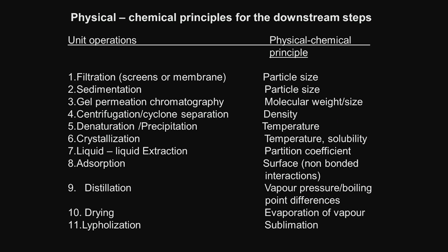For example, filtration, if you take, it works on particle size. So, larger particles are stopped on top of the separating filter cloth, smaller particles go through. Sedimentation again is based on particle size, larger particles settle down. Chromatography, for example, gel permeation chromatography works on molecular weight or size difference. So, different sizes come out at different times, and we are going to spend some time on that later. So, different sizes of biomolecules come out at different times, hence the separation.